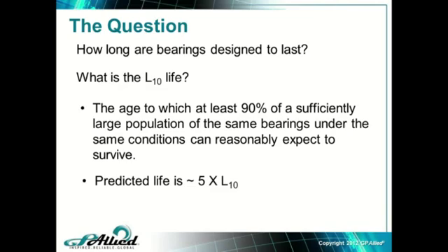And that very thing right there is why we start this presentation with how long are they designed to last, how long are they supposed to last? Because we want to challenge that paradigm that, well, every 2 years they go bad and we replace them, and we've gotten very good at replacing them every 2 years. So, you know, that bearing is supposed to last 2 years. No, that bearing's supposed to last the same as everything else, about 5 times L10. If it's not lasting that, there's a problem. And it's some of those problems we're going to talk about in this presentation and how they manifest themselves in a failed bearing.